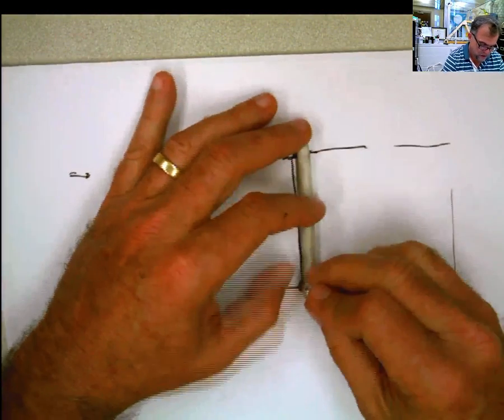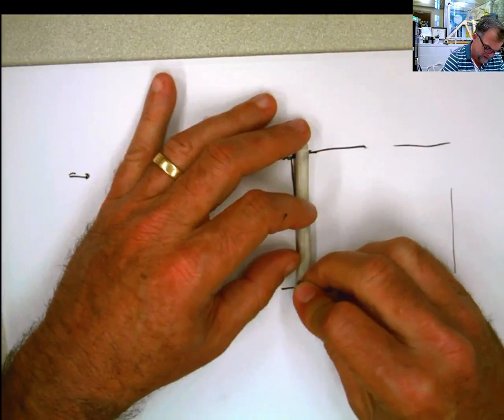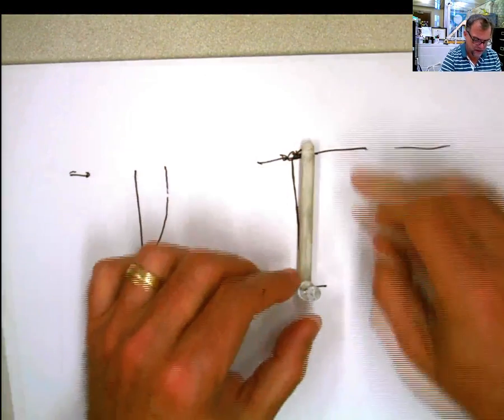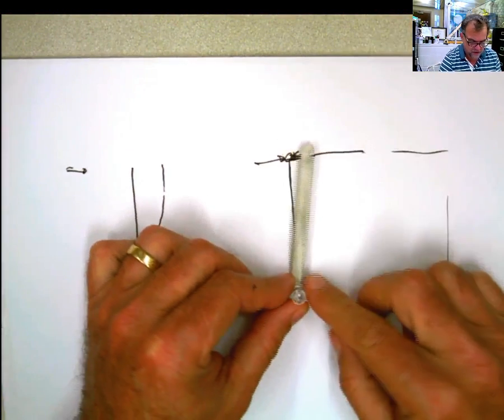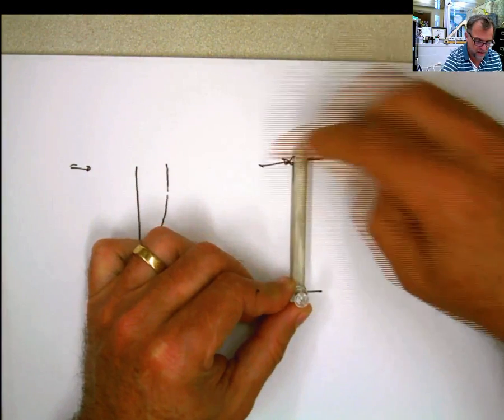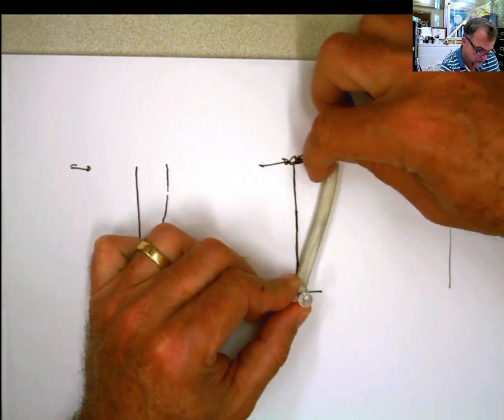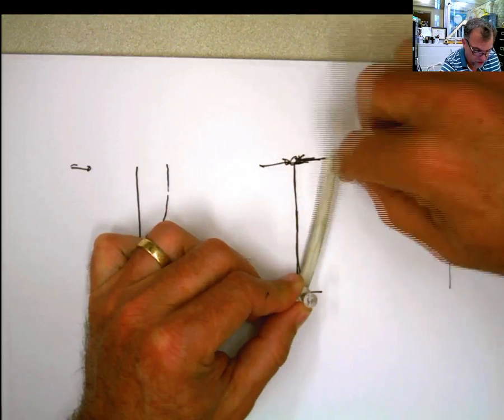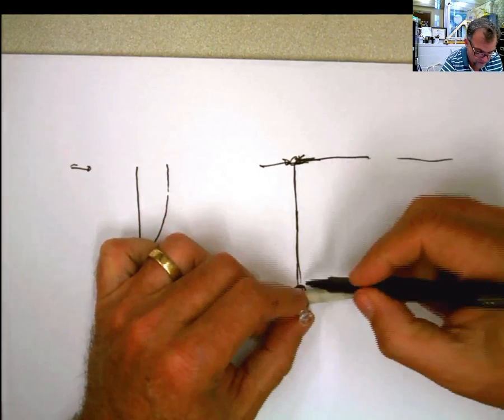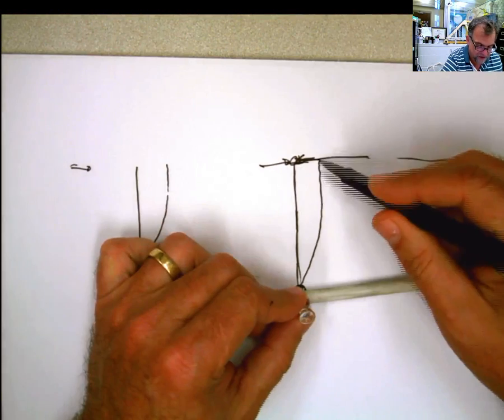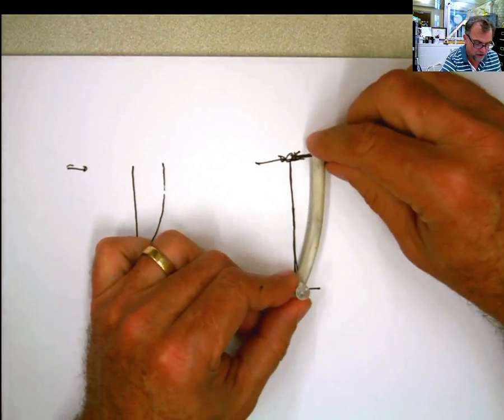I'm gonna put the hinge there, because this is what a hinge is. So if I put a hinge there in that point and apply the load, this is gonna be the diagram, you see. Assuming that you have some restraint here, the diagram is gonna show this shape, which is the shape that you can find basically in every literature explaining how the shape is like that.